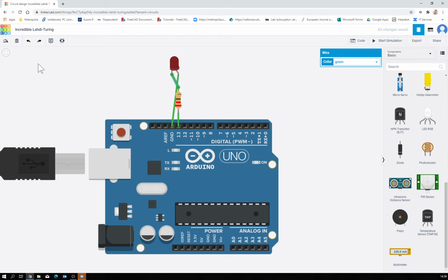So no blinking, because the current flow and voltage were the opposite of what it should be. The positive lead should always be on that bent wire here. That's one hint. Another one, a reminder: try to make this look neat.